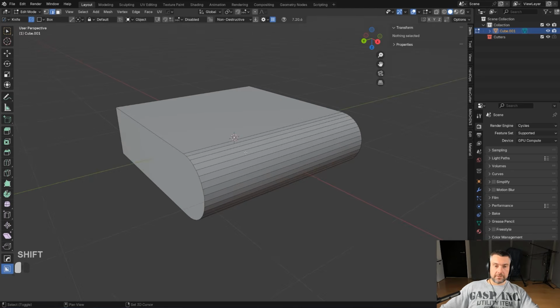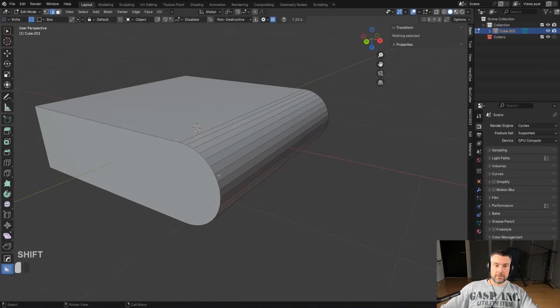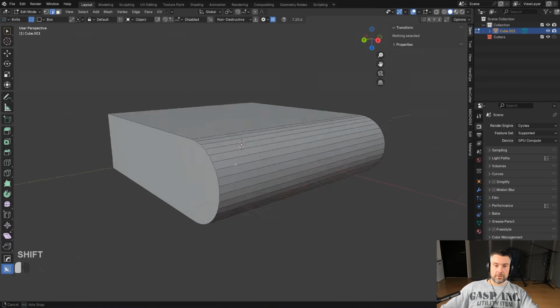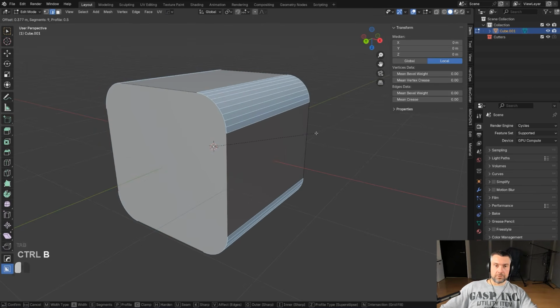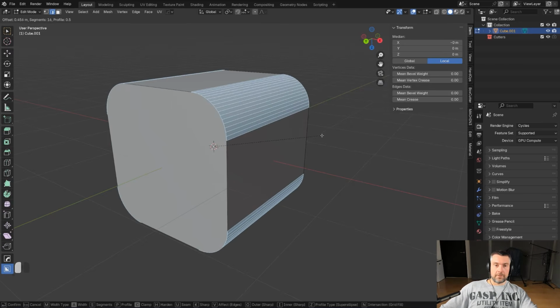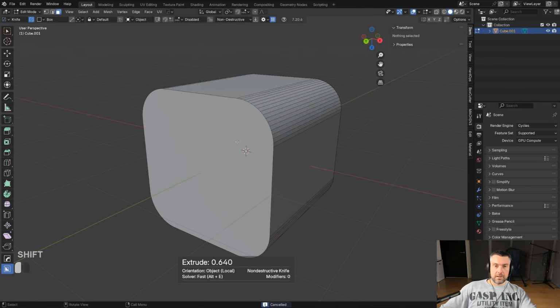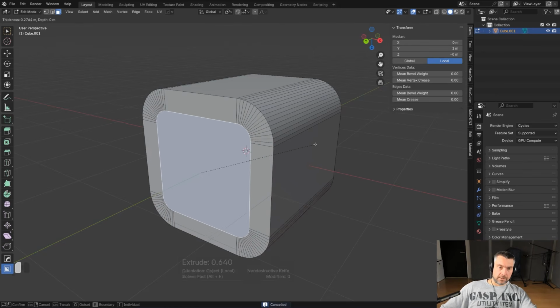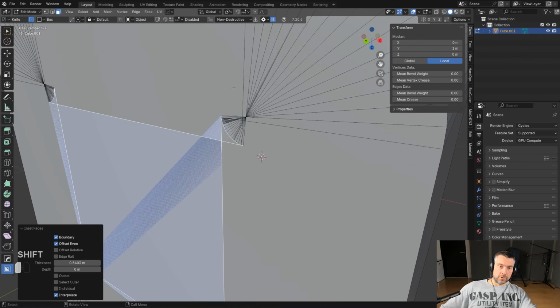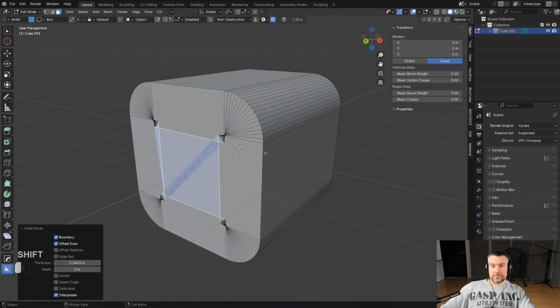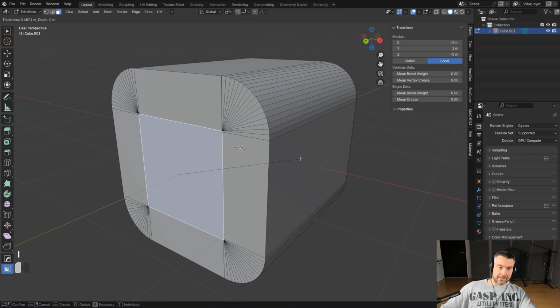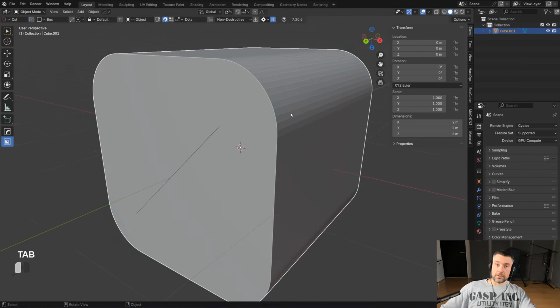Okay, so we cleaned this up and now you've got this really nice bevel, and you can have fun with this one. Let me show you something else with bevels. This is something you should pay attention to. It's really important. Let's grab bevels here, and let's say we wanted to inset this face, and you see eventually when I go too deep, my bevel is going to overshoot on itself. It's going to invert and flip inside out, and my geometry is going to be distorted. Sometimes you don't see problems like this, especially when it's minor, a tiny clipping like that. You may miss this when you're modeling very quickly.